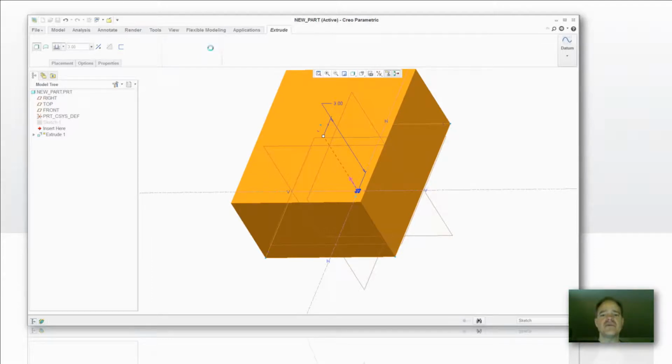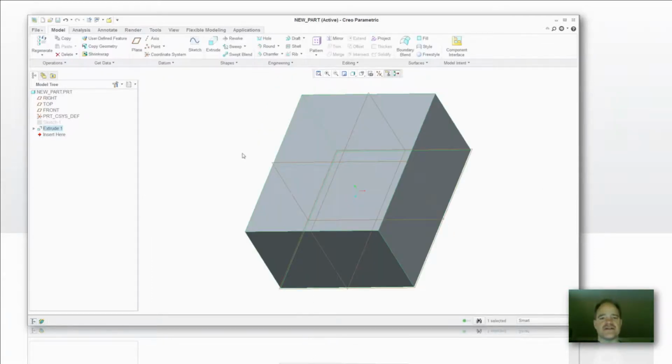Okay? And that only works for the first feature, because once you've got a feature established, your graphics within Creo Parametric are going to scale down accordingly and then give you representative values from that point forward. It's always that first feature that you create in that first sketch that personally drives me bonkers, that I get these stratospheric values that I need to make a major edit to in order to commence and move forward with my modeling. Now, once you've got that done, save that to your start template.